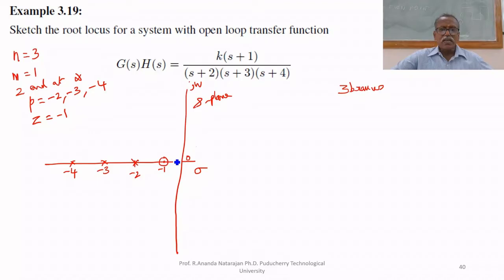But if you select any point between minus 1 and minus 2, it is part of the root locus. Therefore, the root locus starts at minus 2 and ends at minus 1.